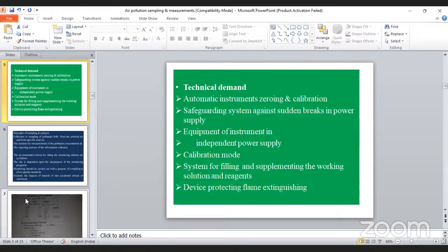When we want to do analysis and it starts raining, we have to take out our sampler and fit it back again, so the calibration and zeroing will change. Doing everything manually takes a long time. To avoid that delay and interruption, adopting auto zeroing and auto calibration methods will be helpful.